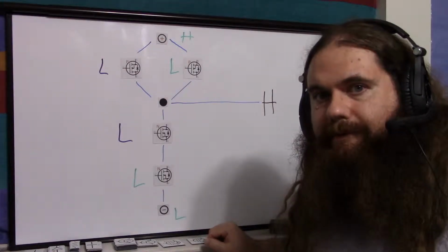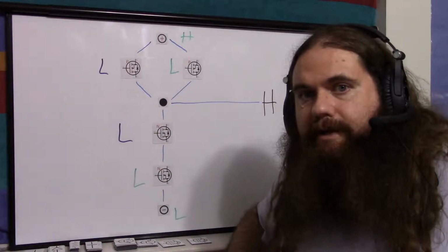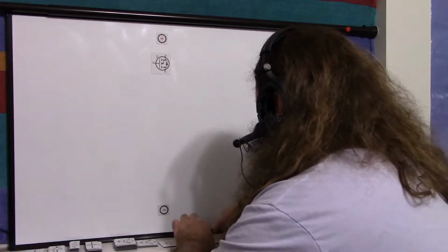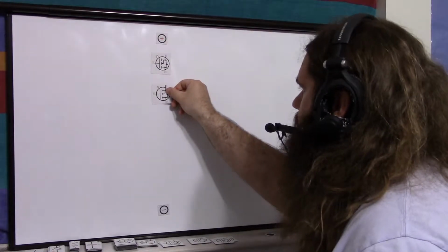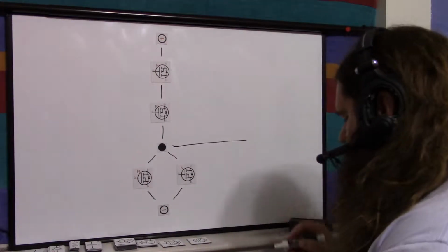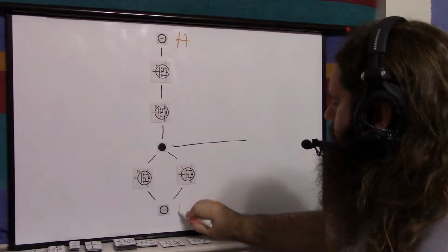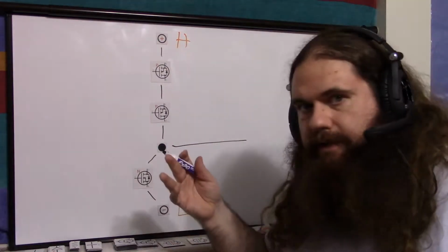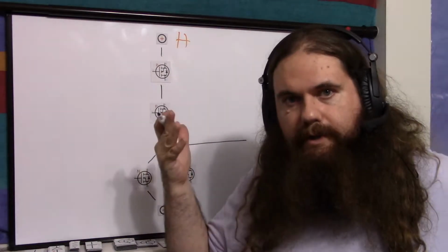What about a NOR? Well, the beautiful symmetry. Don't I love symmetry? Let's put it in reverse. Let's take our 2 P-type MOSFETs and put them in series, and then the N-types, these in parallel. So there's the output. Positive is high, negative is low. So let's say input 1 is the top P. Oh, and the logic. So a NOR gate. We're doing a NOR gate now.